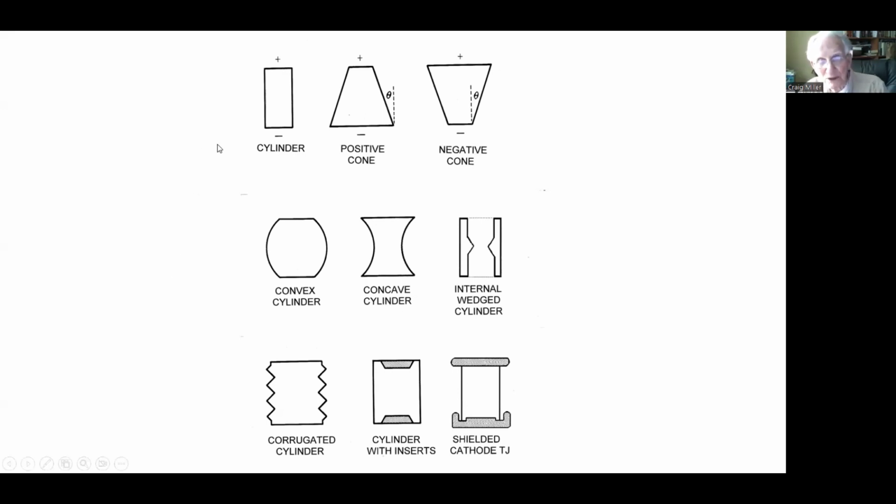Now, it's also found, and of practical importance, that the surface flashover voltage is a function of length. For very short lengths, it's proportional to the length, but as you get to longer lengths, a few millimeters and longer, it is less than proportional, and for longer insulators it's proportional to the square root of the length.